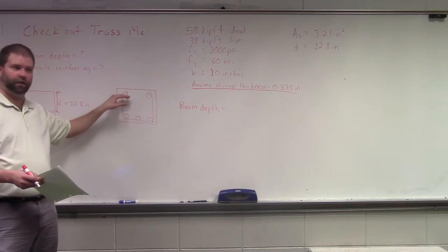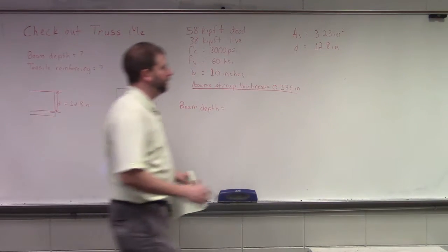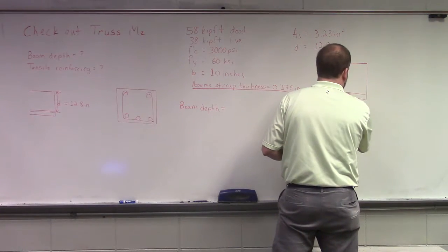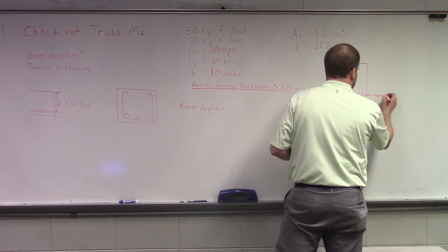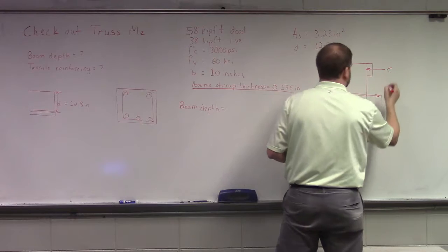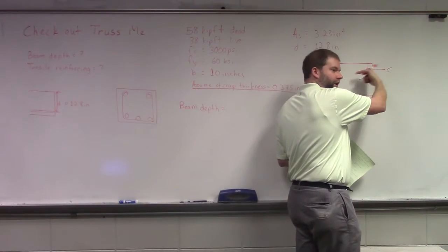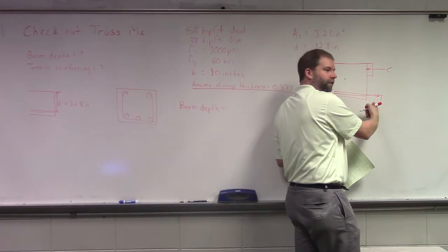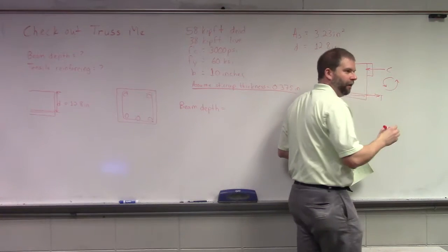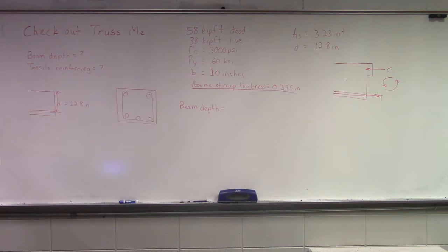The steel in the compression face is not a portion of this determination, because what we're attempting to do is balance out the force that's shearing and compression on this beam with tensile force, so that as they try to rotate each other, they balance out and don't spin the beam out, okay? That's a very good question.